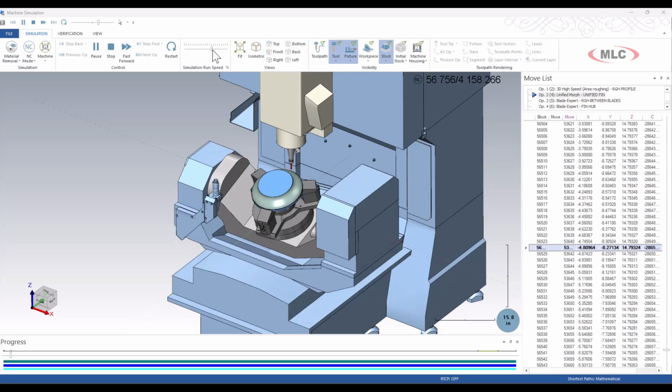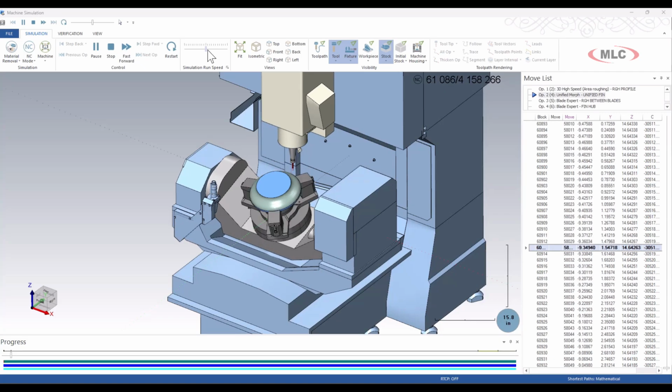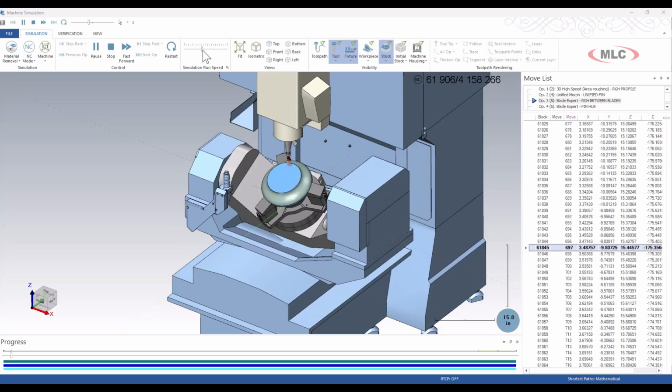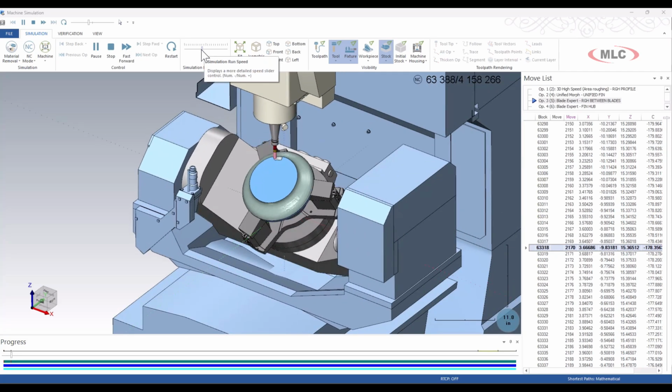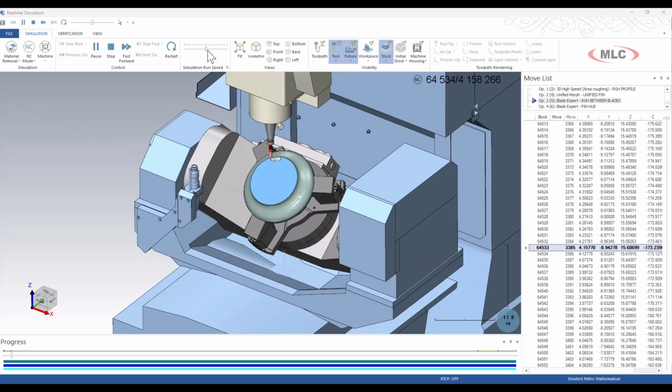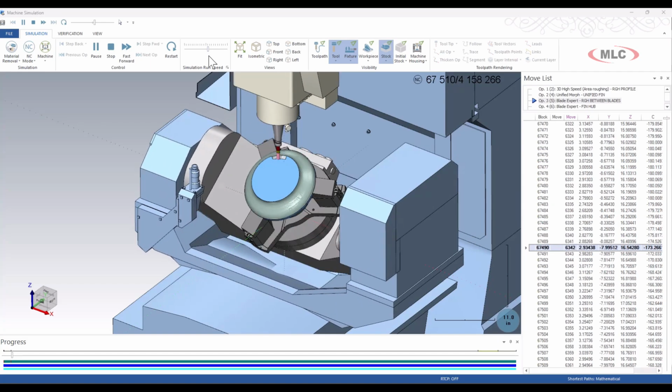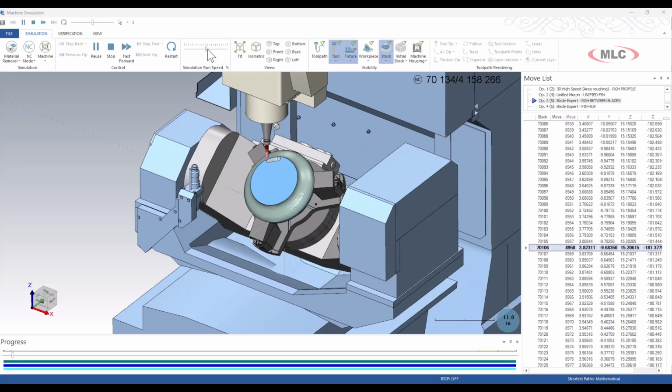So once the finishing of the outside is done, we can see that we have a real nice clearance. There's no red of the chuck hitting the spindle. We can swap our tools and we can come in with that bullnose end mill, roughing out the outside. This is going to allow us to see if there's any kind of collisions as the table moves around.